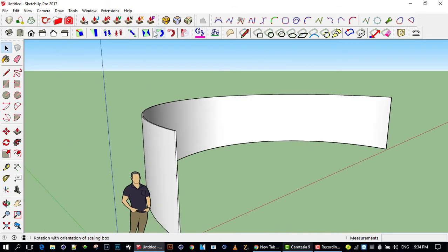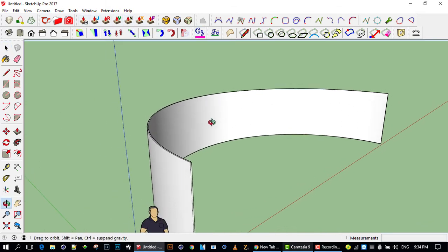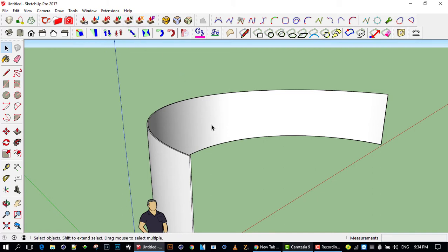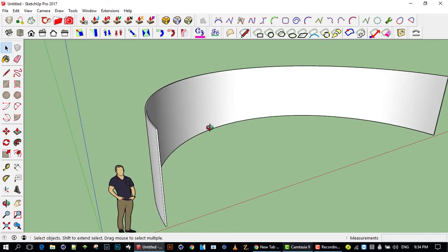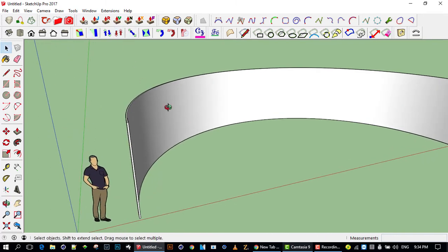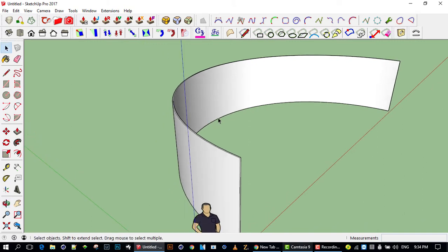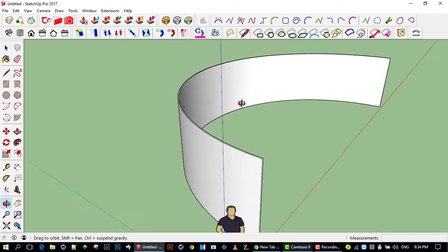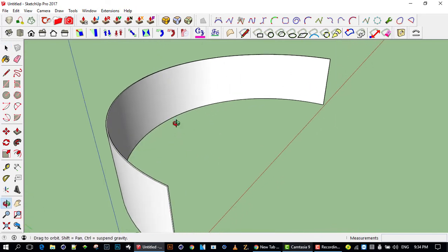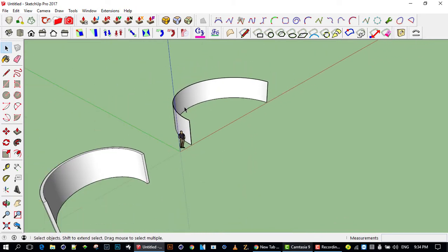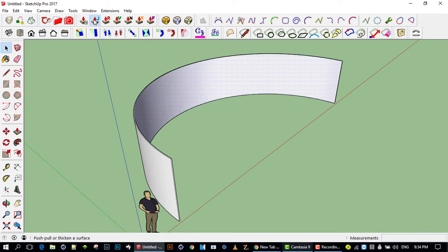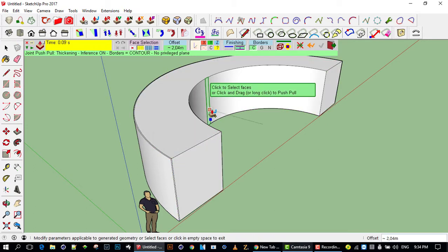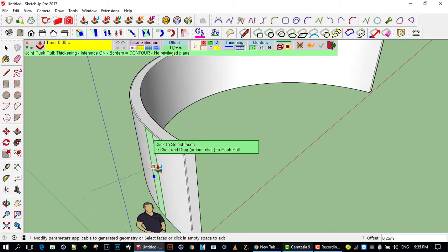And that's the power of using the extrude tool. Now the other tools do a lot of things, but I'm doing this session just to inspire you to actually get to use these tools and show you which ones I use quite regularly and how they help me. So if I decide I want to thicken this wall now, I don't sit with the dilemma that I had before. I can go in there, do the same thing, push-pull tool. I can pull it out and say 25 centimeters, and there I have it.